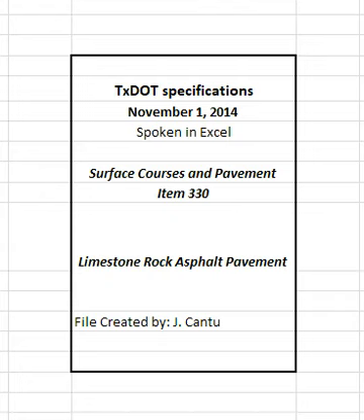4.2 Stockpiling of LRA. Provide a smooth and well-drained area, cleared of trash, weeds, and grass if storing LRA at the project site. Stockpile, handle, and load LRA in a manner that will minimize aggregate degradation and segregation. Avoid contamination and mixing of stockpiles. The engineer may reject stockpiled materials that come in contact with the earth or other objectionable material.